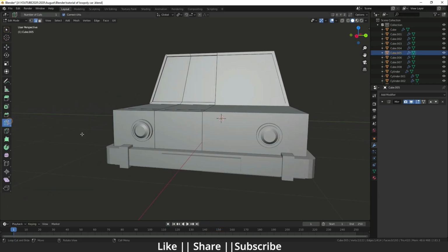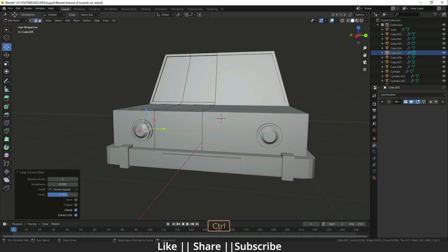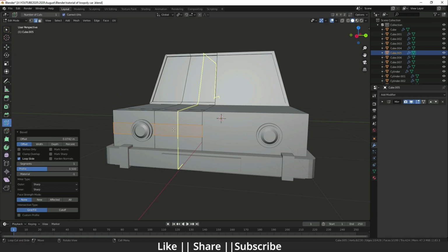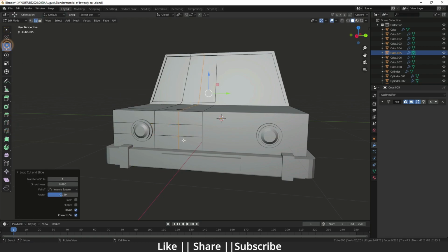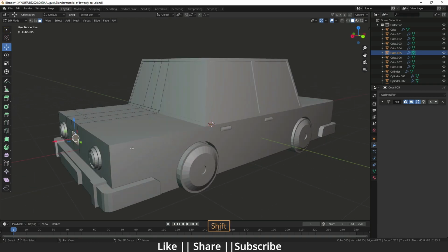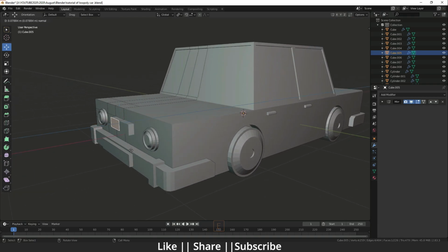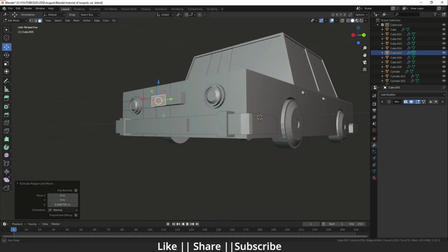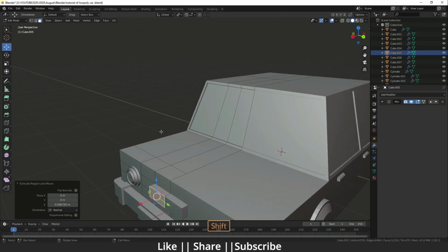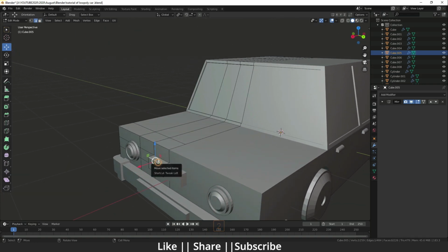So now I'm just going to add one edge loop here, and I'm going to bevel it like that. I'm going to add one edge loop here also, and extrude that face like that, and bevel that edge.